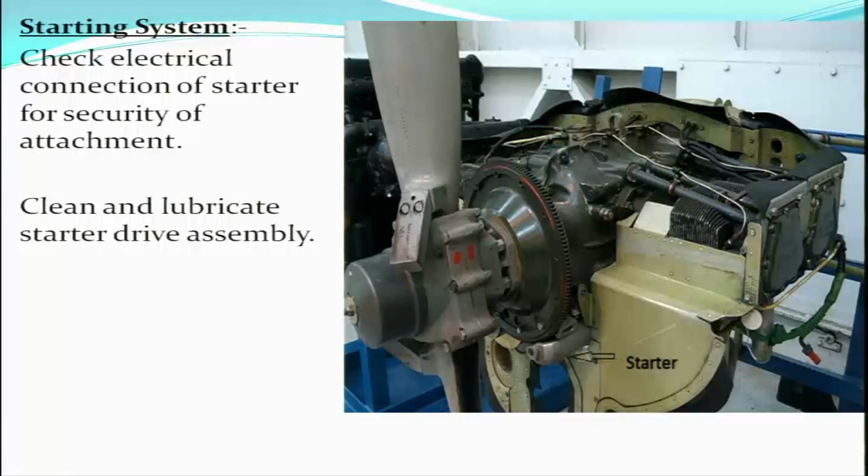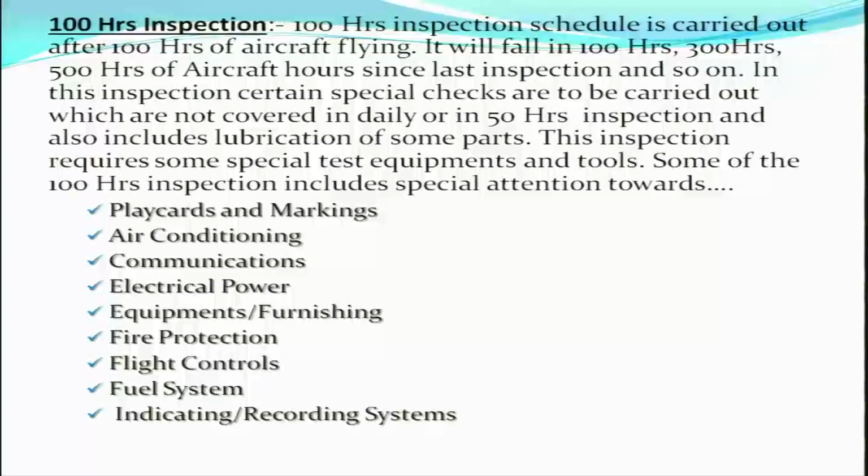We also clean and lubricate the starter drive assembly. There is a starter drive assembly here. We will clean it and lubricate it with the lubricant as specified by the manufacturer in the maintenance manual. This was all about the 50 hours inspection. So we have seen the daily inspection and the 50 hours inspection.